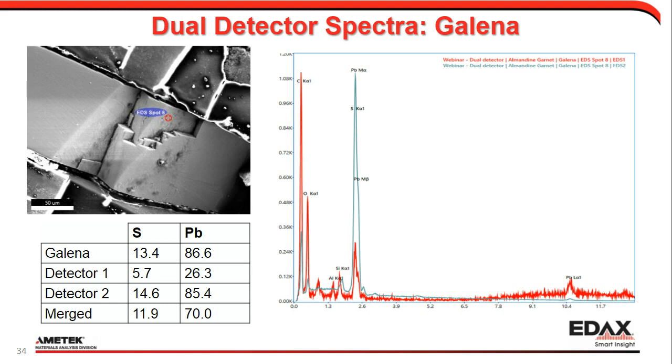But some of these will be going through the epoxy we have outside the sample, and some of it will be going through the lead sample, the Galena sample itself. The stuff that's going through the epoxy and some of the other things that go through can fluoresce the carbon and oxygen in the epoxy that's embedded in. And that's what we see here in the low energy range, that we have very high carbon and oxygen peaks that we did not see before in the flat part of the sample.